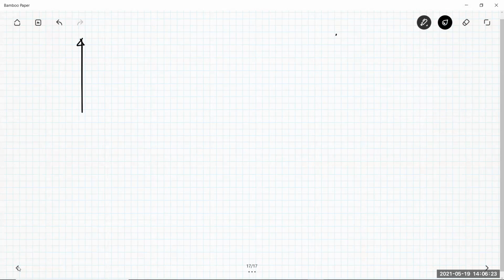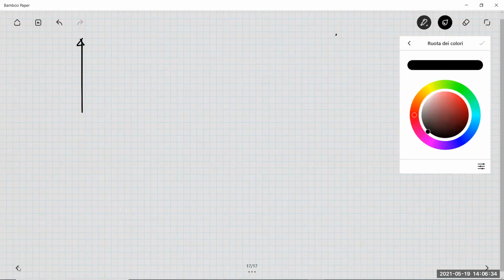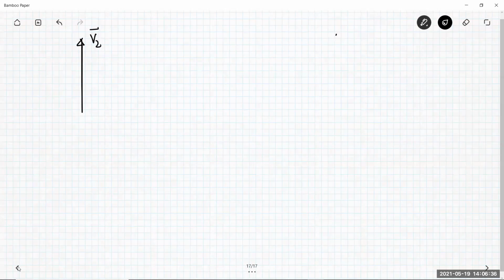But for other angles, how can I compute T1 and T2 exactly to synthesize that position? This is the answer. For that computation, I am supposing that the rotating vector is inside sector 1, so I'm using V1 and V2 to synthesize it.